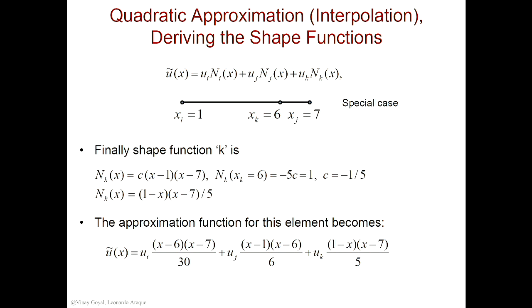To have completeness, we should be able to represent rigid body motion. We showed that in the last lecture. And then we must be able to represent constant strain rates, or constant temperature rates if you're looking at a heat transfer problem. So the physical meaning is that they're mathematically formulated to allow you to accomplish things you could not do before in that manner.